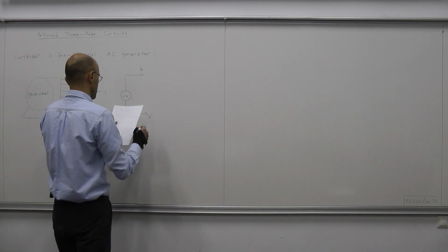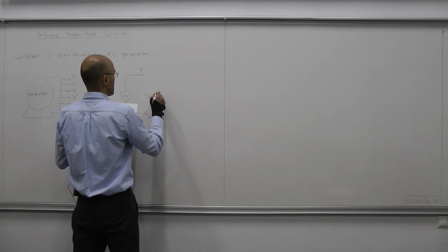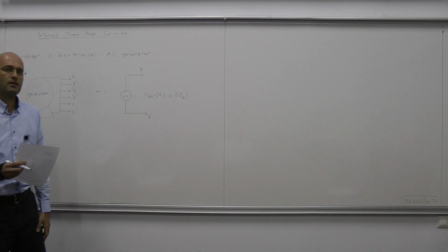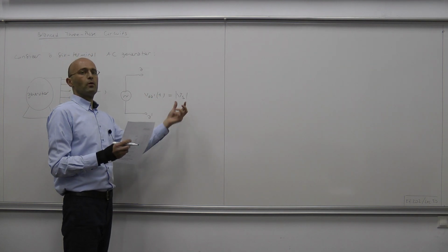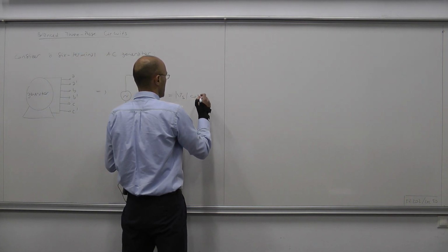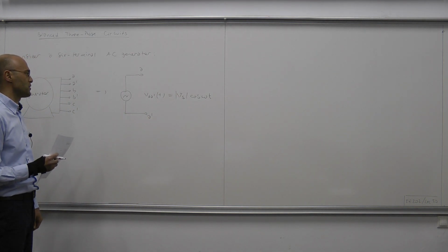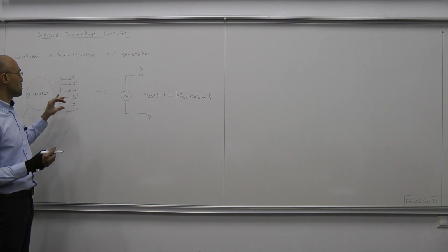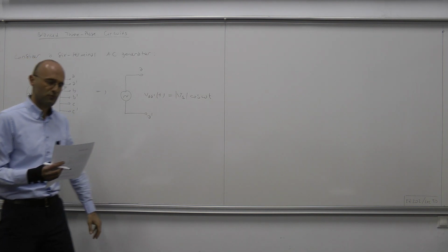Okay, and we have V_AA'(t) equals a sinusoidal signal with some magnitude, which we call the source voltage magnitude, Vs, times cosine omega t, omega being the frequency of operation. And then similarly we have another independent voltage source representing the voltage drop between terminals BB prime, and likewise for CC prime.